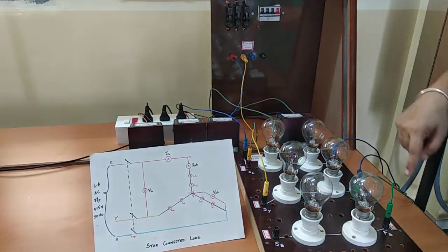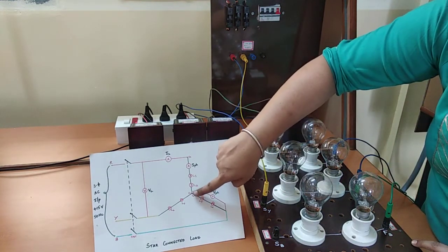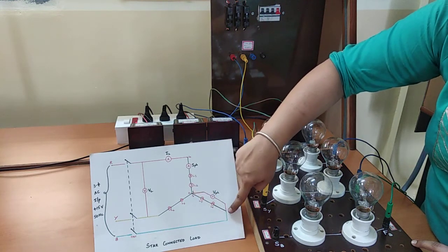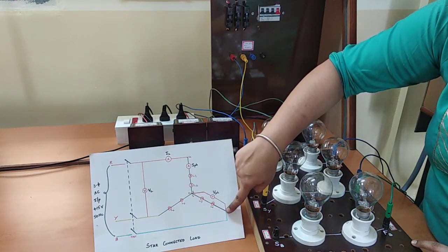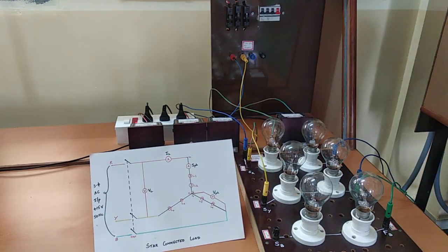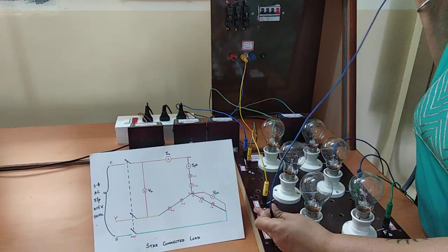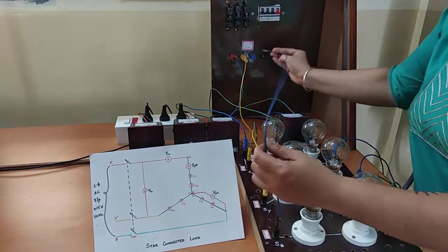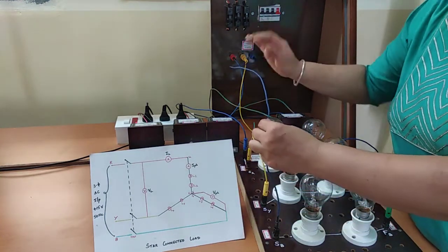Now, we also have connected FB to the neutral, isn't it? Now, the other end of FB is SB. SB is connected to B terminal, blue terminal, the input of B. So, from SB, it is connected to B terminal.